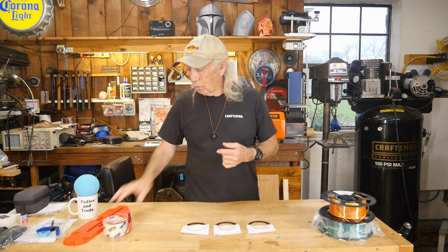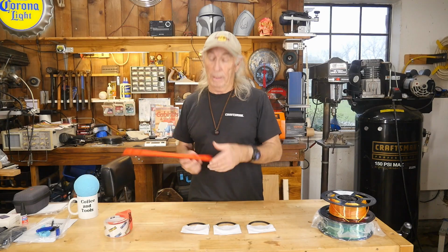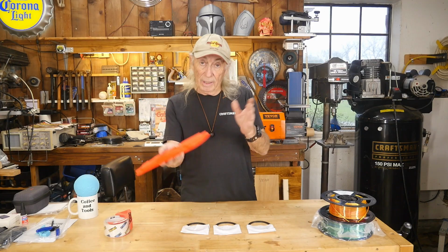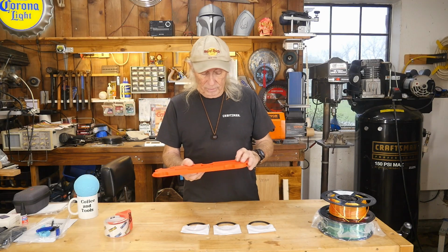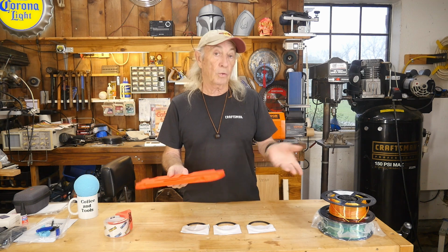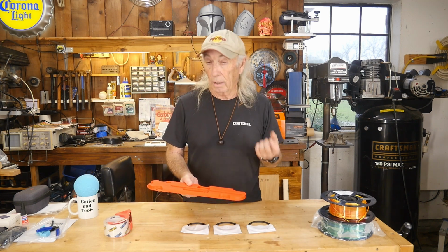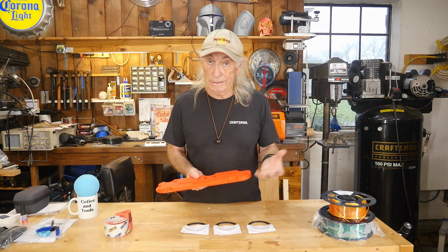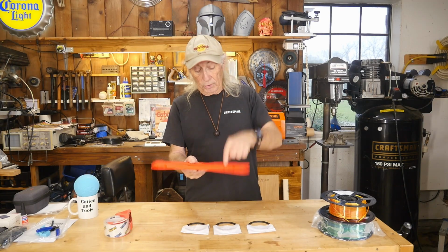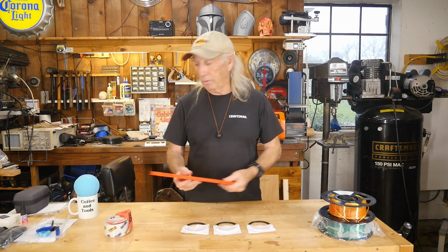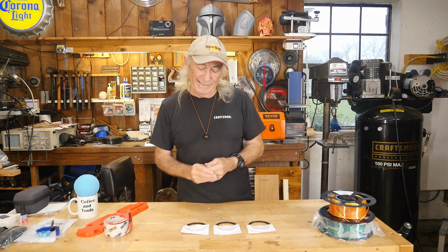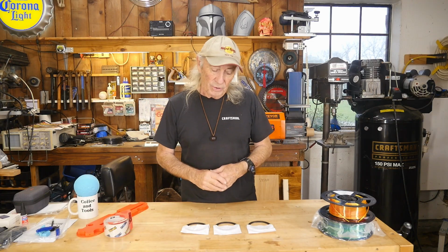Because once I tried again with the new update, I was able to take something like this and have it modeled out and go, oh, I want to punch a hole here. Let's try it now. Hit the Q, there's the cylinder, bang, it's red, which indicates it's going to cut the material away and push it through and create the hole I wanted, which was like, yes, this is what I'm looking for. So it's the new update that they did in February.